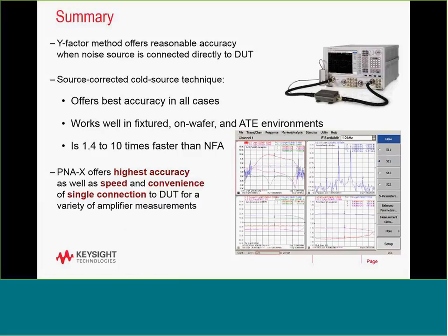To summarize, the Y-factor method offers a really reasonable, easy setup to make DUT noise figure measurements. The source-corrected cold source technique offers the best accuracy in all cases, works well in fixtured, on-wafer and ATE environments, and is faster than the noise figure analyzer in most cases. So, I'd like to thank you for listening, and I hope this has given you some information in terms of what would be the best technique for you to make noise figure measurements in your near future.